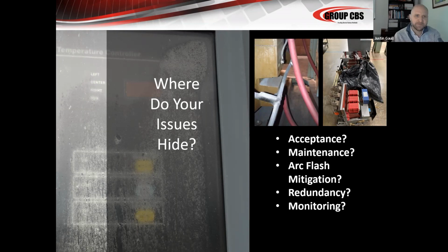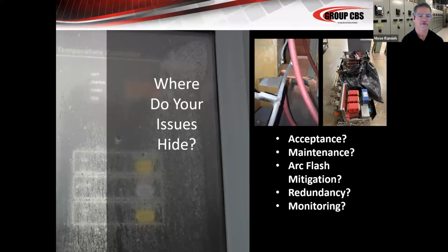One thing that's coming to mind for me is we didn't talk a whole lot in this about lubrications. Obviously, that's a pretty critical thing too for your general maintenance. And I guess you have experience dealing with that. We deal with that in our service shops, but also in the field a lot too, right? Yeah, lubrication in the field is one of those challenges. We all talk about it. We all recognize there's challenges. The one thing I would warn our viewers about is the use of spray lubricants, like WD-40 is an easy example that everybody recognizes, but there's other types of penetrating spray lubricants.